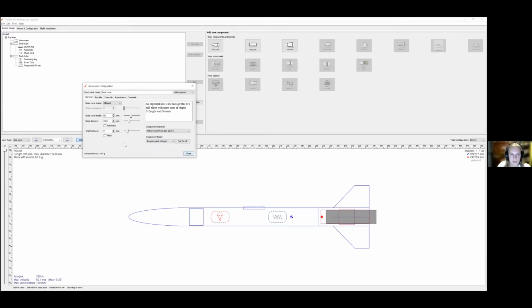When we talk about the wall thicknesses of 3D printed parts, we need to keep in mind that we want them to be a multiple of 0.4 millimeters, because the nozzle of a 3D printer is 0.4 millimeters. And so when it's laying down beads of 3D printed plastic, you want those to be sitting right next to each other and neatly make up the thickness of your wall. So in this case, 5 times 0.4, 2 millimeters. So we're going to have 5 wall thicknesses and have a nice strong part.